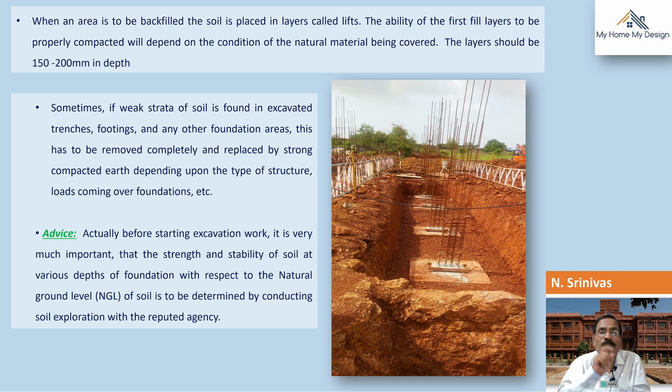See, this is very important. Sometimes if a weak strata of soil is found in excavated trenches, footings, and any other foundation areas, this has to be removed completely and replaced by strong compacted earth, depending upon the type of structure, loads coming over the foundation, etc. This is what I am stressing here.